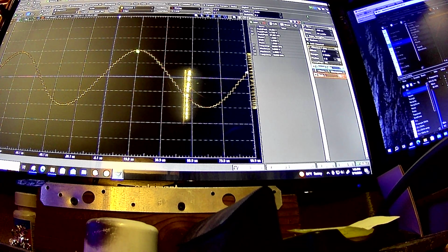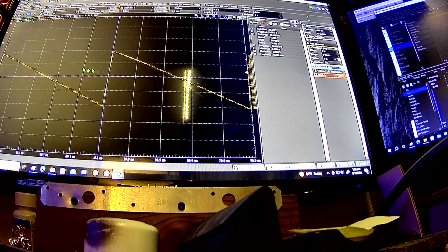This is a 14-bit DAC. So not all these voltage levels are equal, but if you look at a stair step, this is what a 6-bit DAC would look like here. But in any event, the point is we're a lot smoother now. You have more variability, but again, our maximum frequency is 10 kilohertz, and let's see if we can hear it.